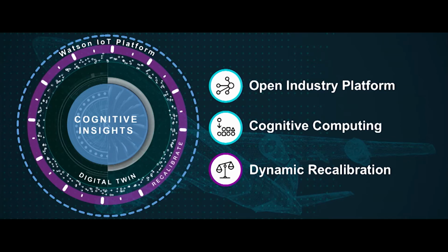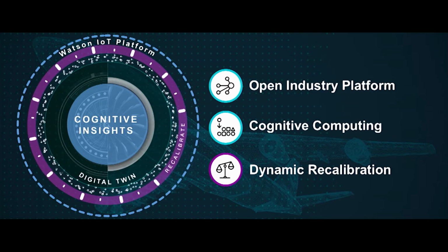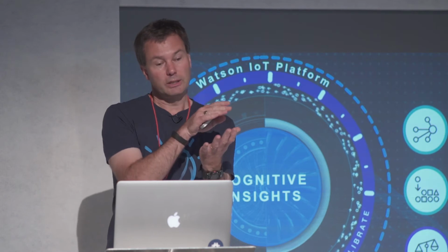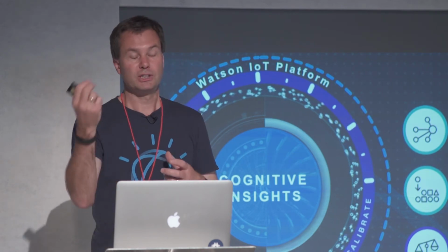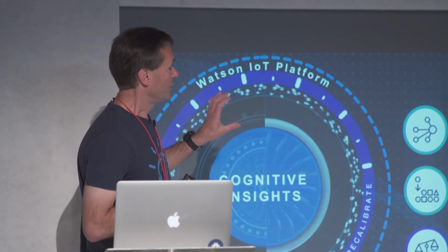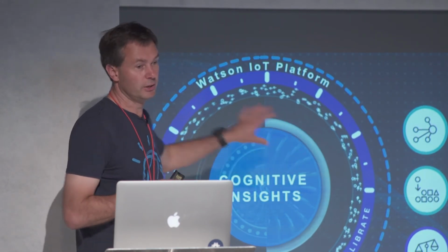And I said, well, it actually depends on what outcomes you're looking for. So start on the right-hand side, as my data scientist friends say. Work out what outcomes you're looking for, then work back from that to work out the necessary and sufficient set of variables from the sensors that you need to make the observations you want, and the synthesized values from those observations in order to drive the equations and the models that you want to build. So we're constantly comparing the reaction of the twin to the physical system.